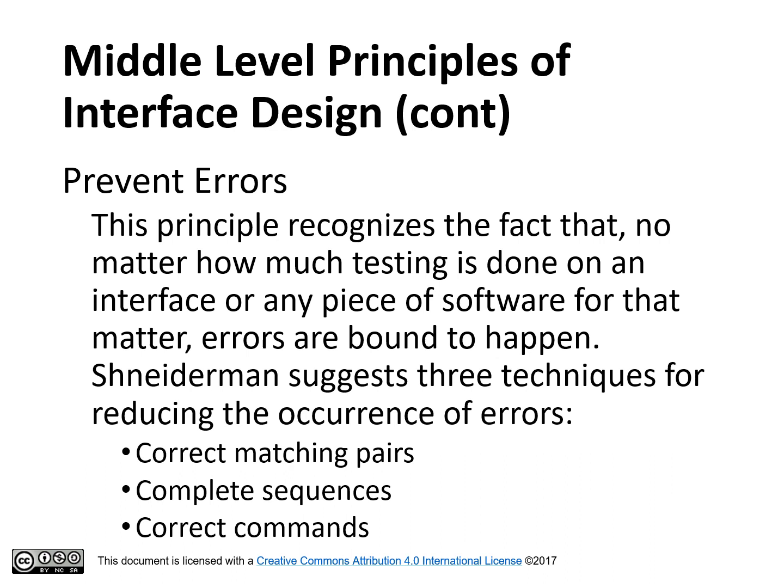The designer must prevent the user from invoking incorrect commands that may jeopardize the safety of the system. An effective preventative measure is to offer the user a choice of available commands through a menu-driven system rather than allowing the command to be typed in.